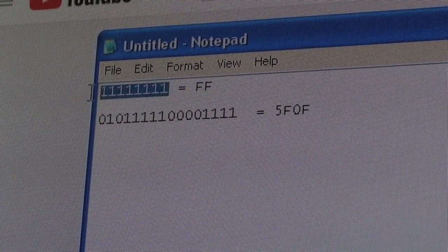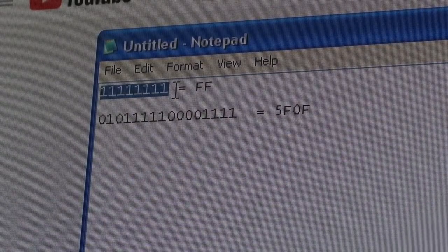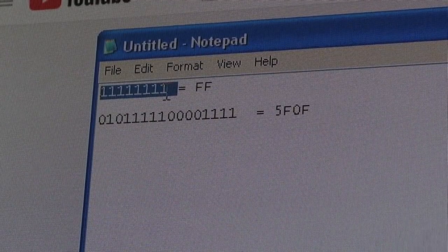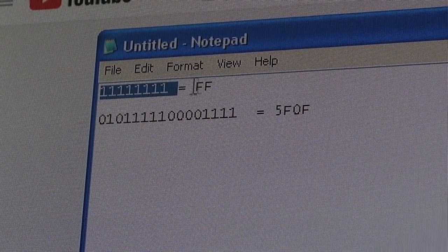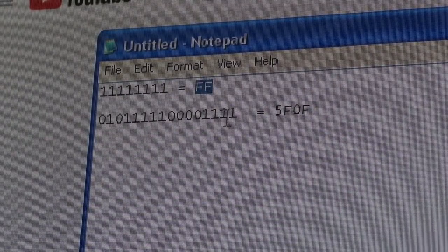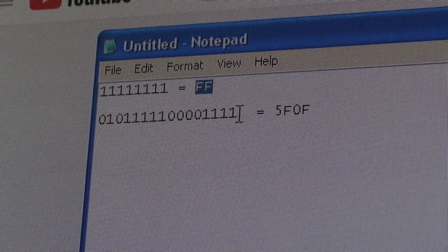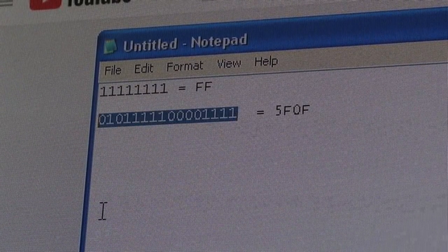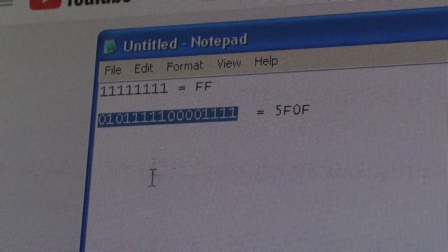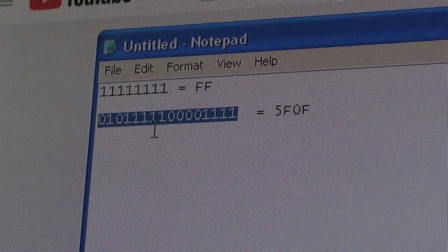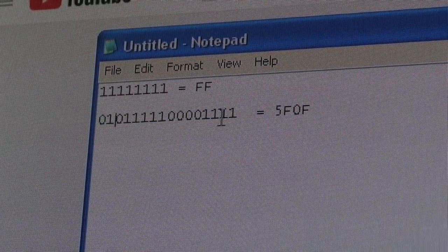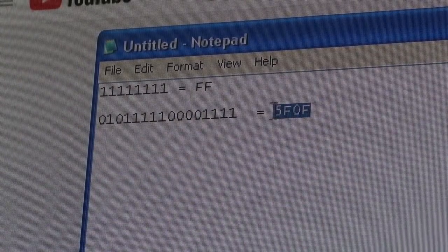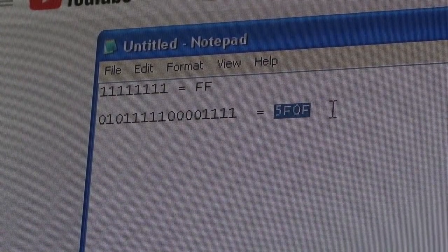Can you imagine a load of code where every time you write to an address, or write a byte or a value, you put in the whole binary in zeros and ones? It could get quite confusing. It's much easier to deal with hexadecimal values to represent those binary values, and it should be more evident if you look at, say, a 16-bit example. Can you imagine writing an instruction to read something from that address into the accumulator? It's really difficult dealing with all those zeros and ones, whereas you can just represent it with 2 8-bit hexadecimal values.